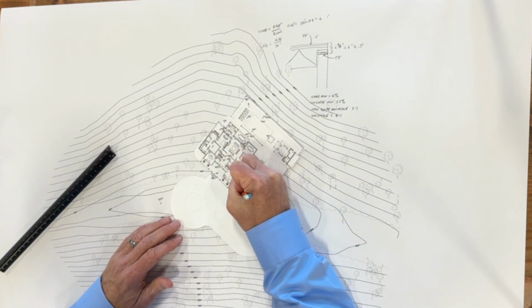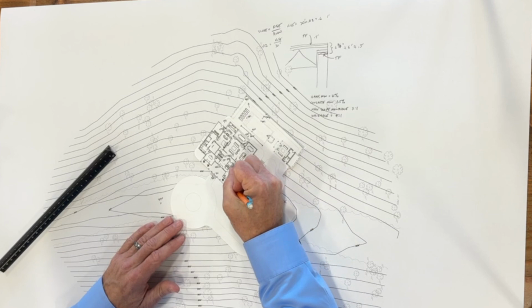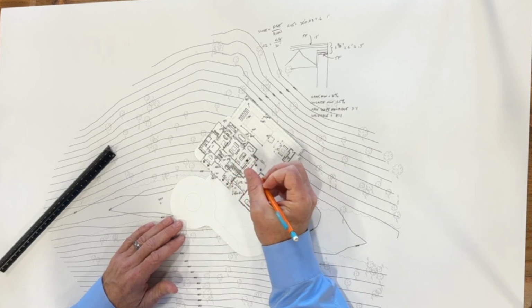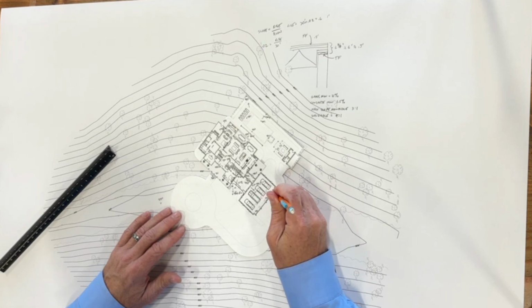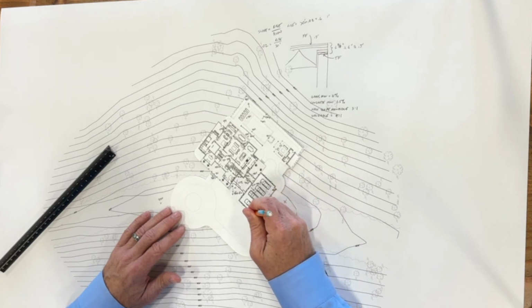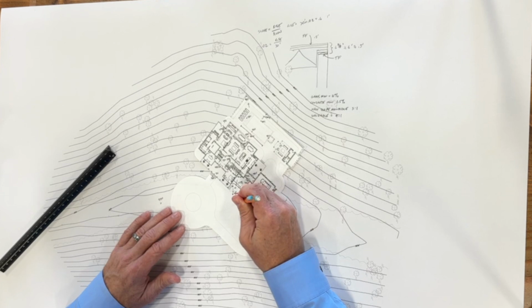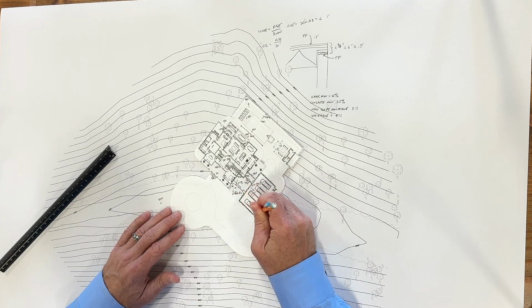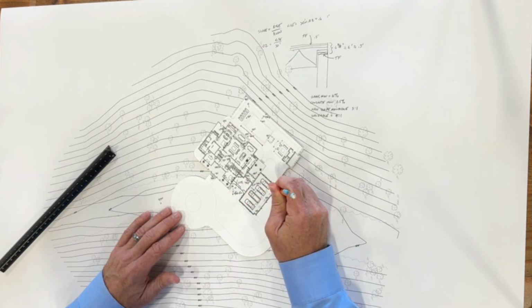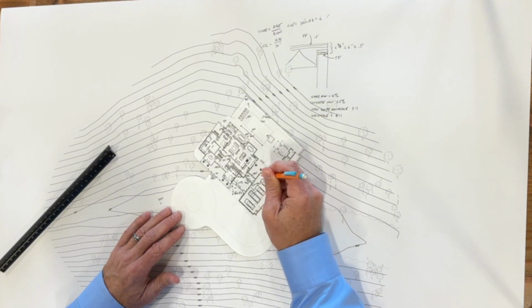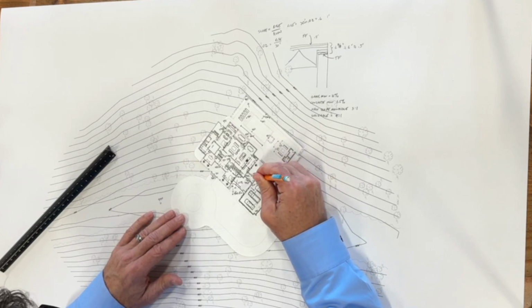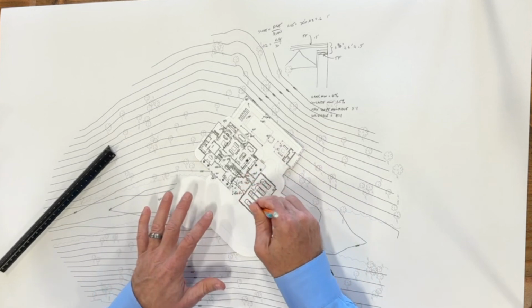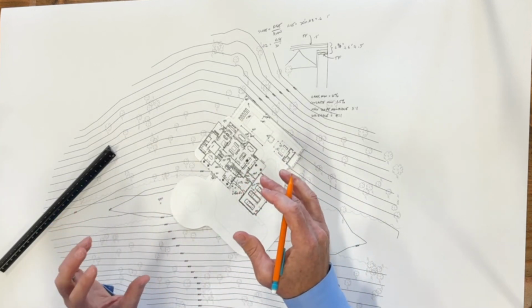And feel free to draw as many arrows as you want all over. So the water is now coming to this spot is where it's going, all right? Now, the 941 is right at that spot. So that means that contour line is like right on the building, right? So this building line, if I'm going to draw the 941, looks just like this, right on the building's edge, right? All the way, in fact, probably just all the way around. That's where it goes. And then you have a 941.5, so it actually kind of comes back here. So you can't really see that contour because it's in the building, okay?